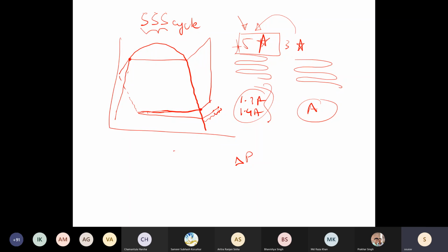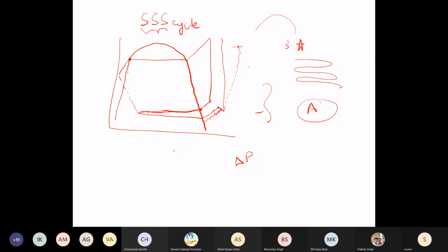Okay, when you come to the lab class, we will see that in case of hermetically sealed compressors, you cannot avoid the useless superheat. Okay, then you can have some pressure drop again as the vapor enters the compressor. Okay, because of the pressure losses in the valves, and also there are pipings inside the compressor assembly itself. And then instead of going an isentropic compression, you will undergo some non-isentropic process. You will end up somewhere here. You will have a larger superheat. Now, remove this. You will end up somewhere here. You will have larger superheat at the exit.